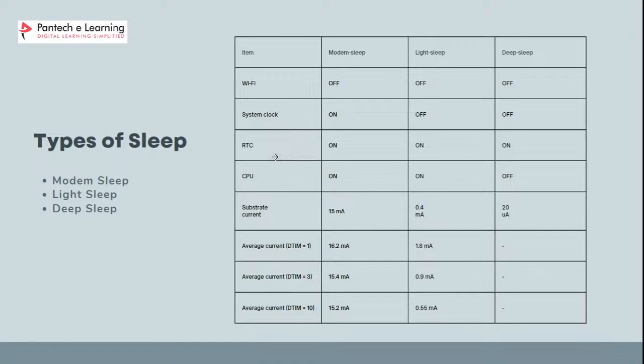The table provides an estimation of average current consumption in milliamperes for different scenarios, assuming the microcontroller is operating at a 3.3 volt power supply. A lower current in deep sleep mode signifies minimal power consumption, which makes this mode suitable for battery powered devices where power conservation is a crucial factor.